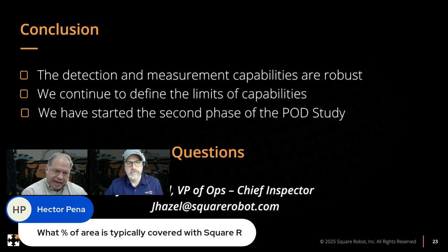Can we perform an EVA or a statistical analysis at 25% and give you an indication of this tank bottom? We're not seeing any corrosion, and we're not really seeing anything that dictates that the tank needs to come out of service and it can't be installed. So, as long as we can prove what that corrosion rate is, there are different levels of inspection that we can run into. It might be that 95% coverage that we can produce, or we might be at 50, 60, 70, 80. It just depends on what equipment is installed into the tank.